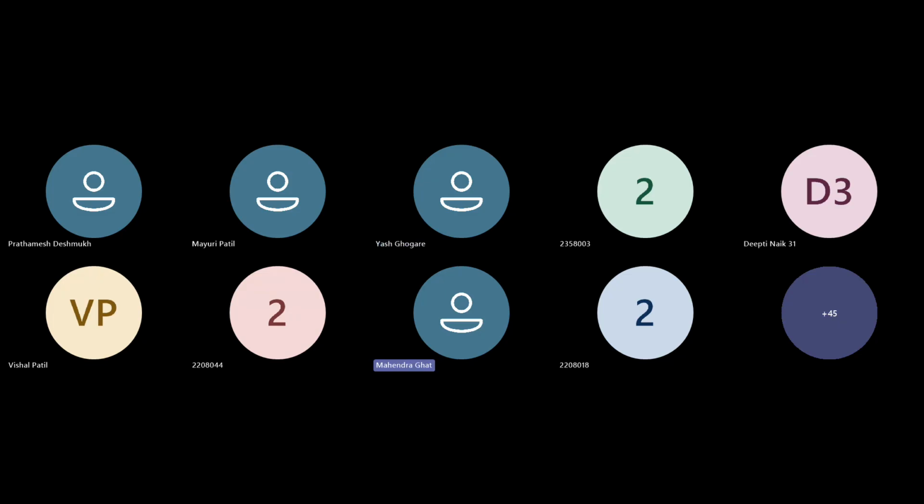Other things like inductor and capacitor design depend on the application. If you are not using a correct capacitor, you will get a higher ripple at the output. If you are using a lower inductor, then you may get discontinuous conduction, not continuous conduction, but you should still get the output.